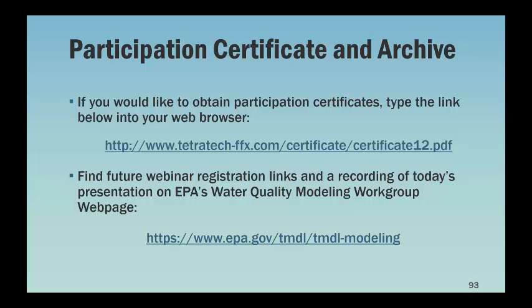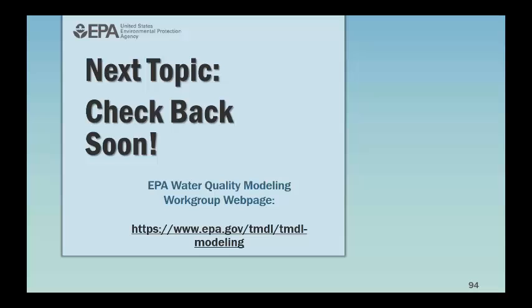So it's widely and well accepted, but I have to admit that not every component of the SWAT model is tested everywhere. The most extensively tested is the U.S. in terms of water quantity and water quality. Most of the other uses, like in Africa and other places, are mainly for land use change, climate change, and hydrology. Not many projects are done with water quality. If there is water quality, it's most likely sediment only, not nitrogen, phosphorus, or pesticide. So that may still be to be explored or evaluated in those water quality modules in many other places in the world.